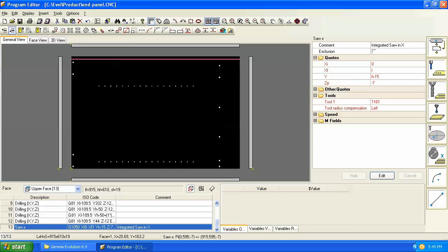In this video, we'll complete our base end panel by making a toe kick in the bottom right corner, and we'll use the routing commands to make the toe kick. So what we want to end up with is a toe kick that's 100 millimeters tall and 75 millimeters into the base and then comes out the end. So we'll start below the front edge of the end panel, go in 75 millimeters and come out the end.